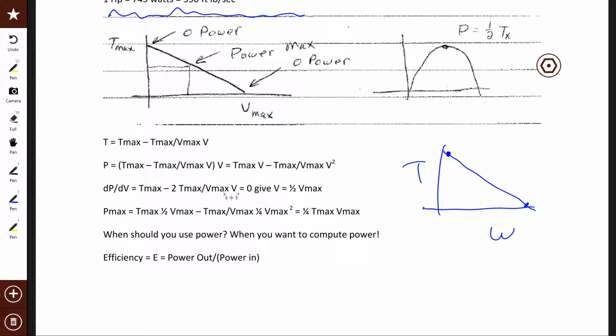For example, if you have a pump, on one end you can say, look, I'm going to run the pump and I'm going to set it up so that it gives me the maximum amount of pressure. Then you'll get very little power out of it, because typically it won't flow. It'll give you a lot of pressure but no flow. On the other extreme, you say, I'm going to let the thing run and it's going to pump as fast as it can possibly pump. It usually gives you no power because it has no pressure across the pump. And that's very typical.